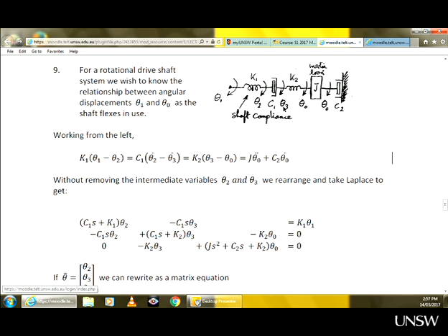Question here. If this is equal to this, equal to 0, right? Well, there's no J, there is no inertia, so the entire torque acting in the spring is transferred to the damper. So it's not 0, it's just transfer. Yeah, they're just equal to each other. It's not zero. So it's basically the force is equal to... No, they're not forces, just torque, because it's all rotation. So ignore force. Why would it be equal?